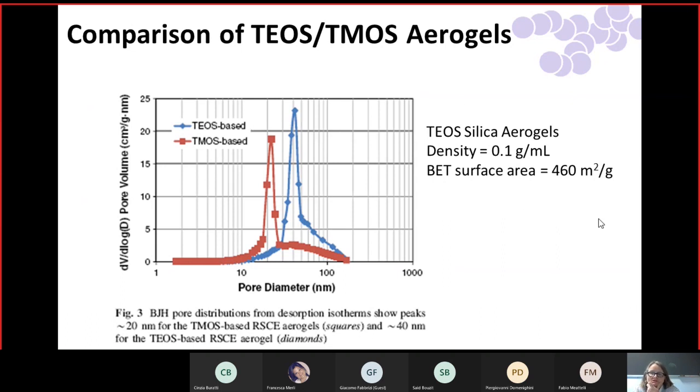So I'm going to stop here. What I have next is some information on imaging, which I'll pick up with tomorrow. So what I've covered here is the methods for density, porosity, and then pore asymmetry to extract information about the pore sizes. Again, there are limitations in what we can do. I talked about open pores, closed pores, the different sort of information you can get, but it's very effective. And I tried to demonstrate with the last few slides that it's effective when you are comparing materials to try to understand what is going on.